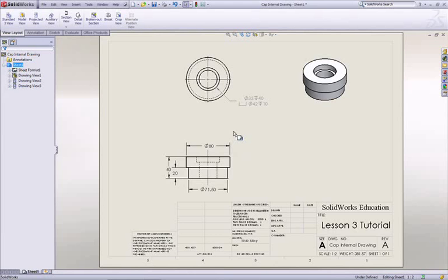When manually labeling dimensions on your drawing, it's important to ensure that all of the required features are appropriately labeled along with their dimensions. This is necessary for a manufacturer to have sufficient information to produce the item. It is also important to ensure that your drawing remains concise by not including repeated or unnecessary labels. You need to adhere to drawing conventions for each feature, such as specifying the diameter of a circle, but specifying the radius of an arc.